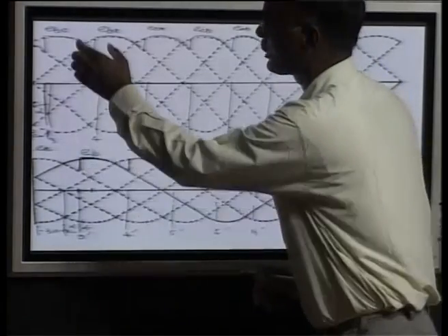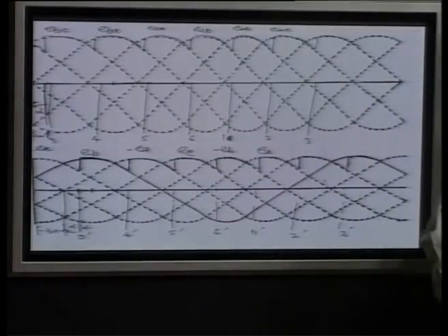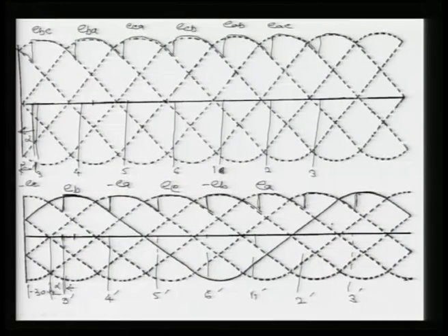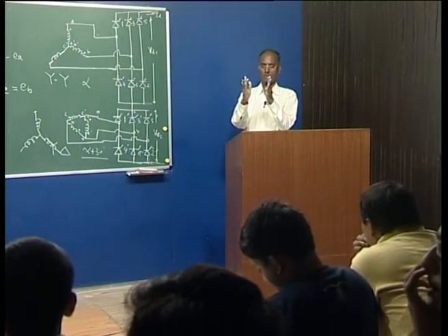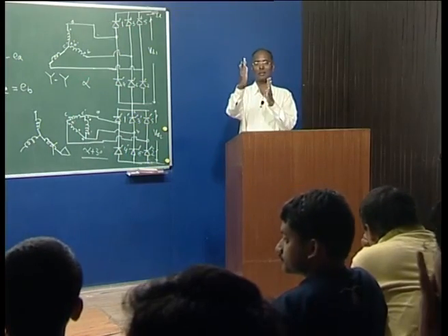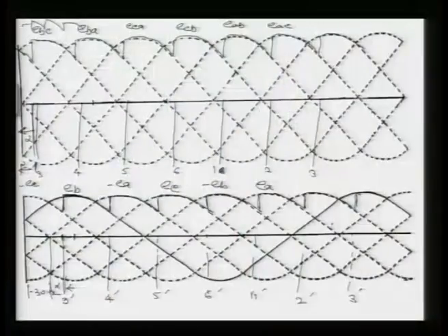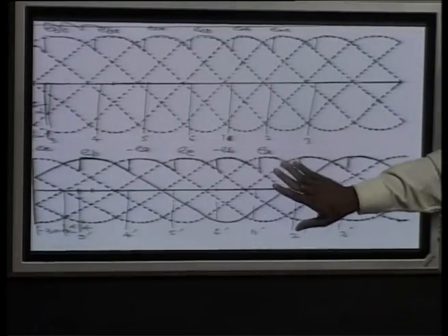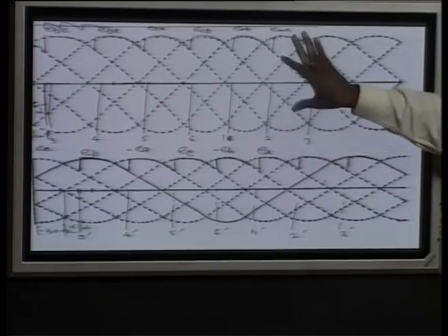So, this is going to be superimposed here, and we are going to get the 12-pulse output. I can simply draw here, this will be our output voltage. This means in one cycle we are going to have 2 pulses in 1 period, because there is a 30 degree shift; each is conducting for 60 degrees, with the 30 degree shift in between. So, we are getting another pulse, and finally we get a total of 12 pulses in a single cycle. So, this is your 12 pulse basically. This is the lower bridge, this is the upper bridge, add them together and you will get it.